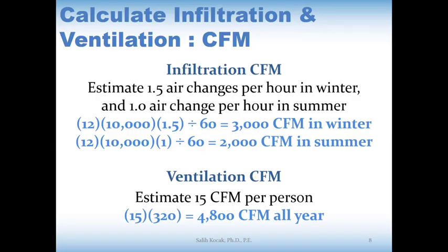If you're using this design, more conservative designers add infiltration and ventilation CFM to allow for exhaust fans and door openings. Again, as I said, it's going to be a really conservative design, and it is not going to help us with good sizing. We will be spending so much money in the ventilation system.